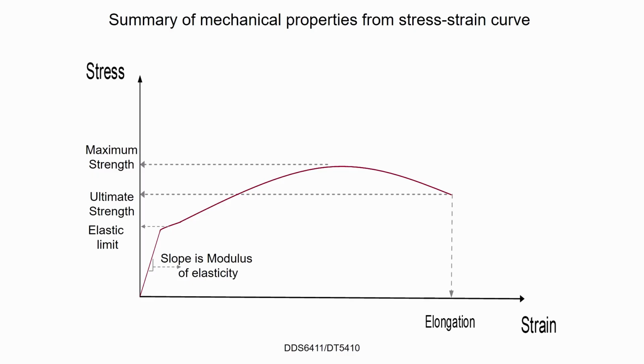Have you heard of necking? I don't mean necking with your girlfriend or boyfriend. It means that under plastic deformation, the cross-sectional area is reducing. You're forming a neck. All right? Because the cross-sectional area is reducing, the effective stress is actually increasing.